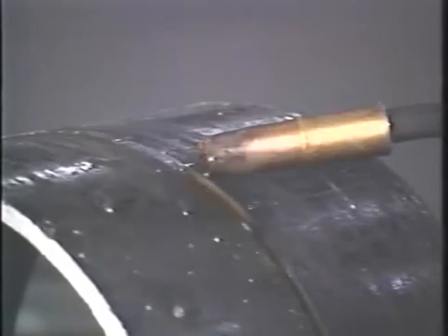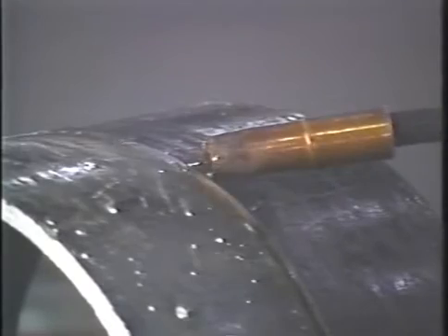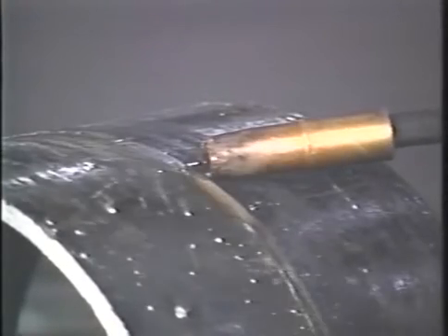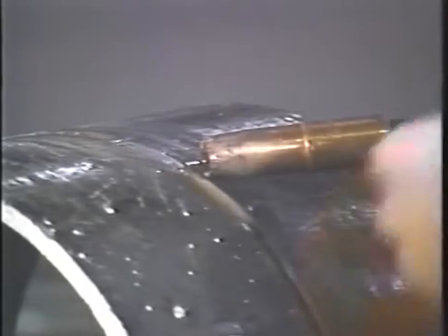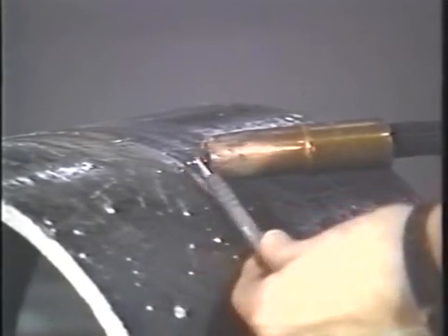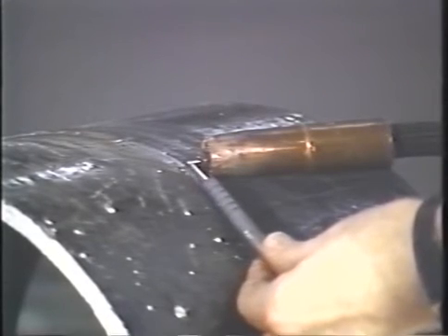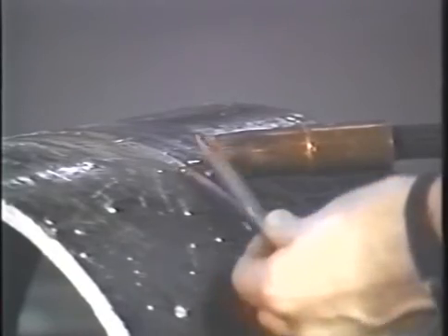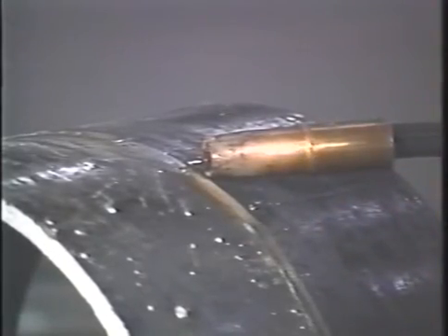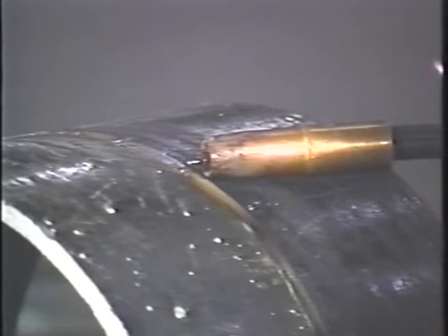And in short-circuit welding, particularly on quality work, on code work, and on very thin sheet metals, wire stick-out becomes critical. Notice on this pipe application that the wire stick-out is approximately 3/16 of an inch. By keeping the wire stick-out small like this, I can use the minimum amount of voltage, which on an application like this is usually around 17 or 18 volts.